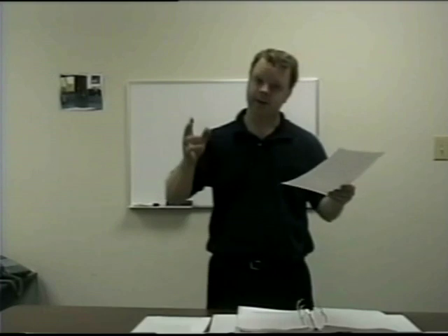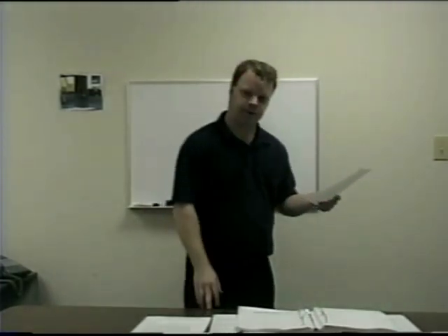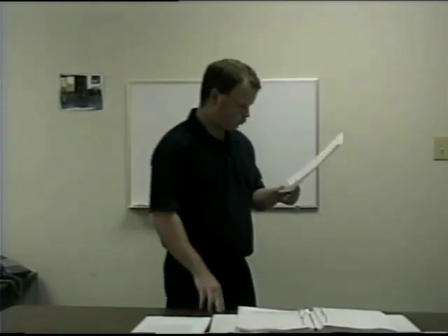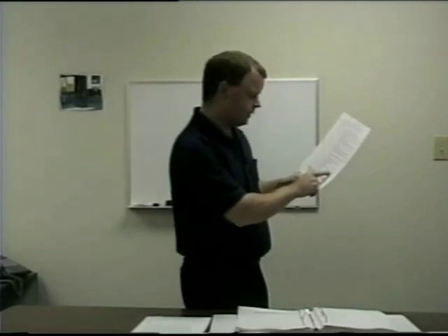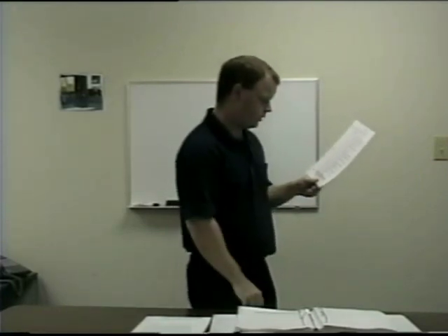Verify finish is maintained or protected and maintained during and after installation. How many times have I seen windows get scratched up? I was going to say windows get ruined, but I've seen frames get scratched up after they've been installed because they were not protected properly. Observe glazing operation. Verify type of sealant is as required, applied in accordance with instructions.